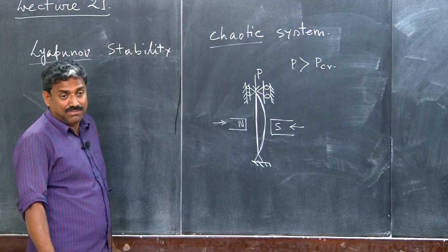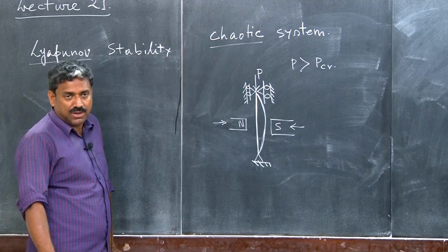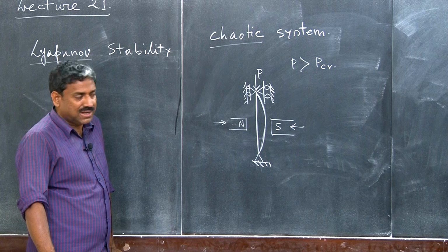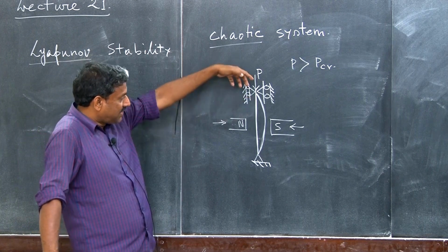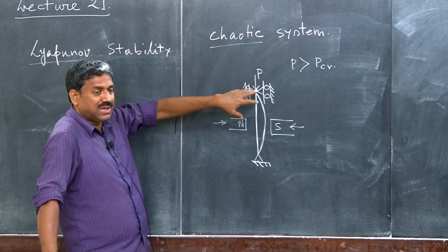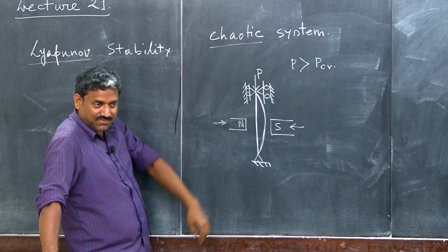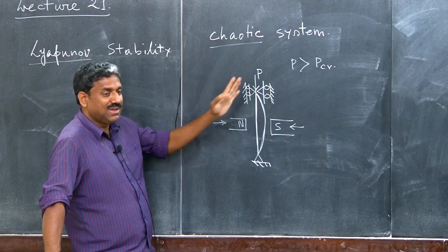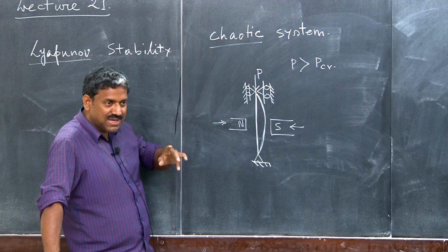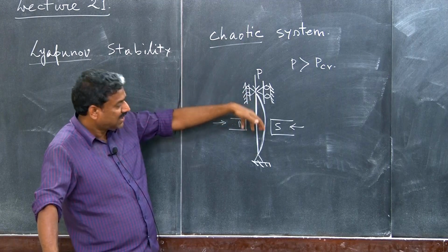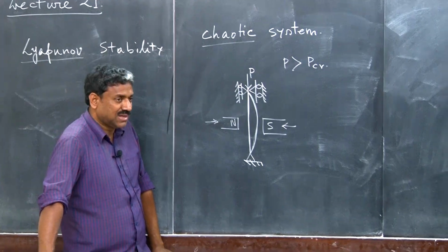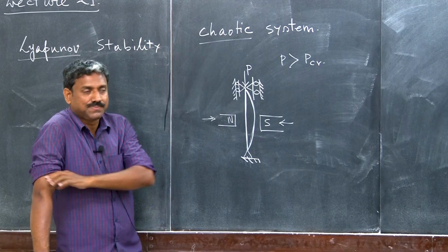This is a column, made of magnetic material, okay, which is attracted by a magnet, and by this kind of arrangement, of course, you can put some bearing etc., and then you can apply different force. So, you can change P, you can make P by tightening. This experiment can be very simply done in a structural engineering lab. It's not a big deal, very simple.